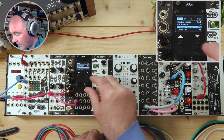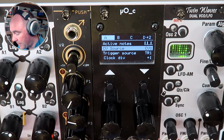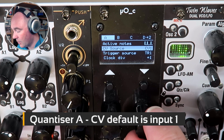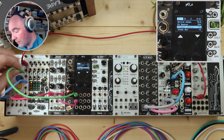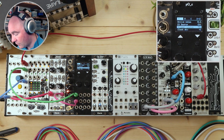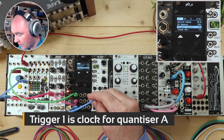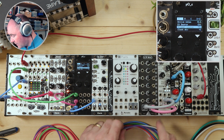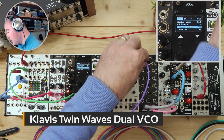Now if we look at the CV controls for quantiser A, we can see that it's expecting a CV source on CV1, but it also wants a trigger on trigger 1. So let's patch clock from our mult here into trigger 1. And I'll patch the output of that into the volt per octave on oscillator 1, and we will patch oscillator 1 into the channel 1.